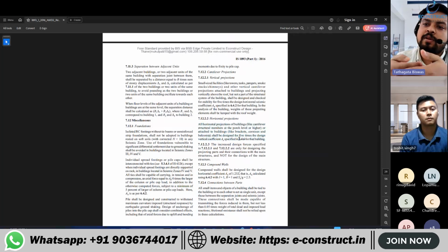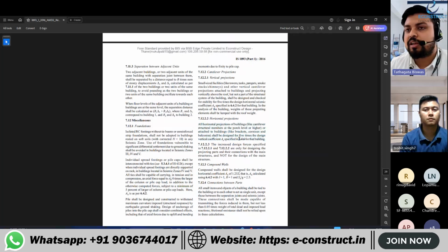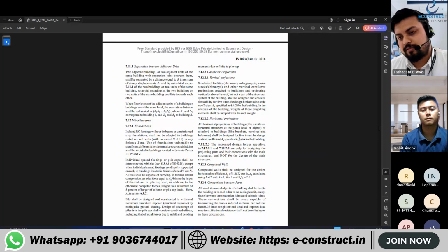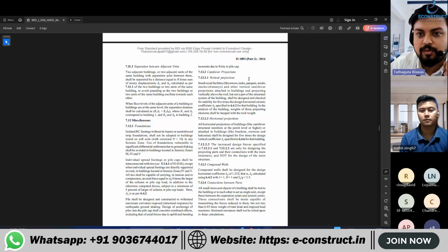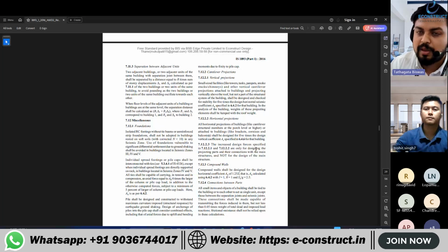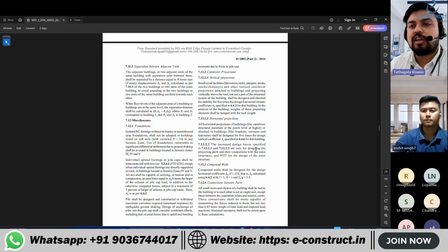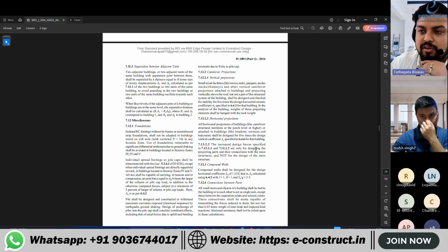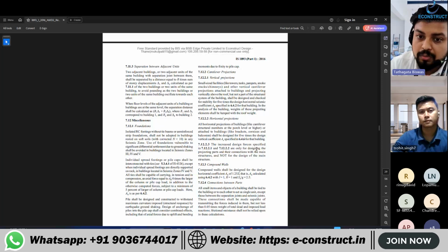So this is just a 1 meter projection. Do you think 5 times of AV will govern? No, sir. You need to check that particular scenario, what is actually there, and take the call. Balcony can be 1 meter, or up to 3 meter, 5 meter also. Till how much should be specified if the code wants to guide us that way, but that is not mentioned here.